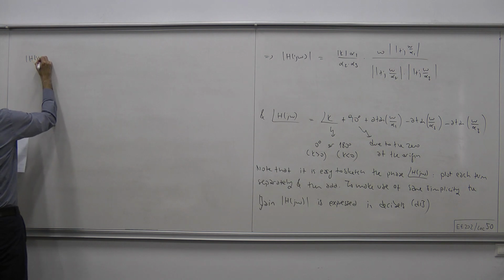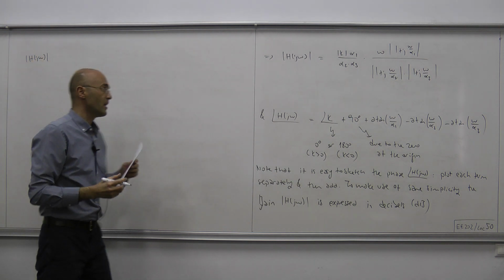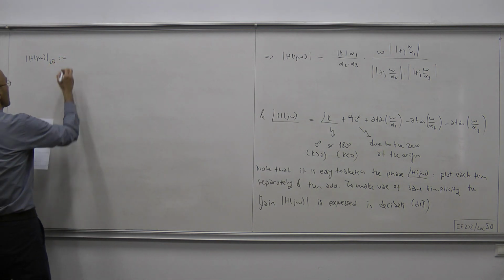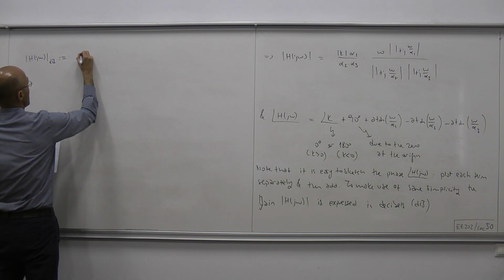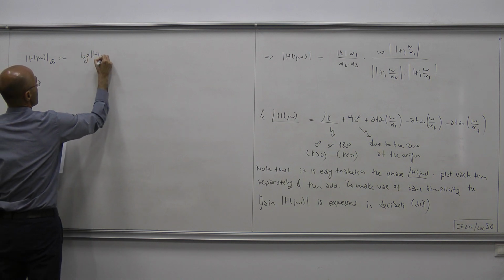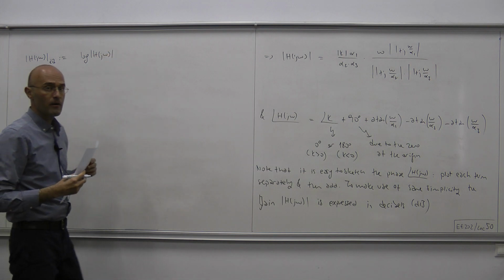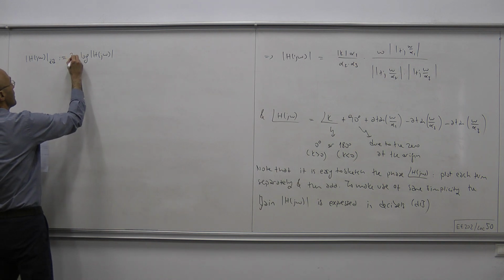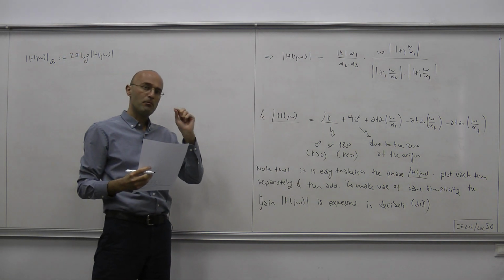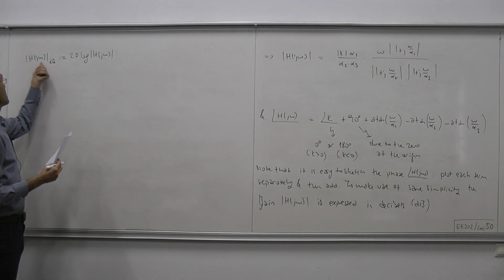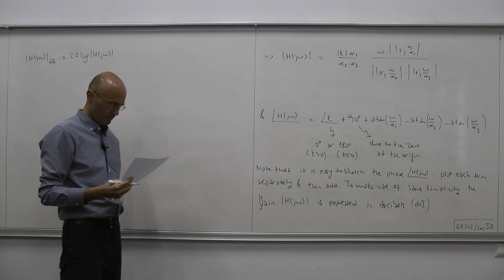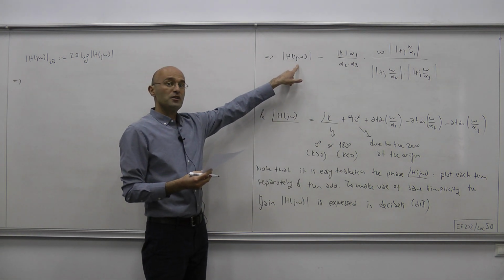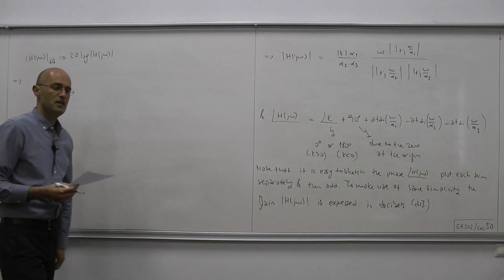H(jω), the gain expressed in dBs, means the following. What you do is you compute the log of that positive real number, the magnitude of H(jω), and then you multiply that by 20. And the new number that you obtain is the gain expressed in decibels. So now let's write the gain once again, but this time in terms of our new units.